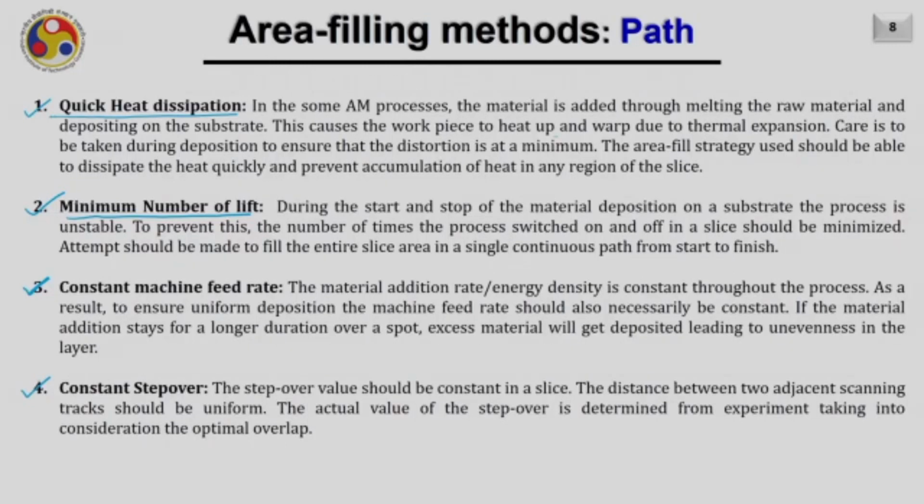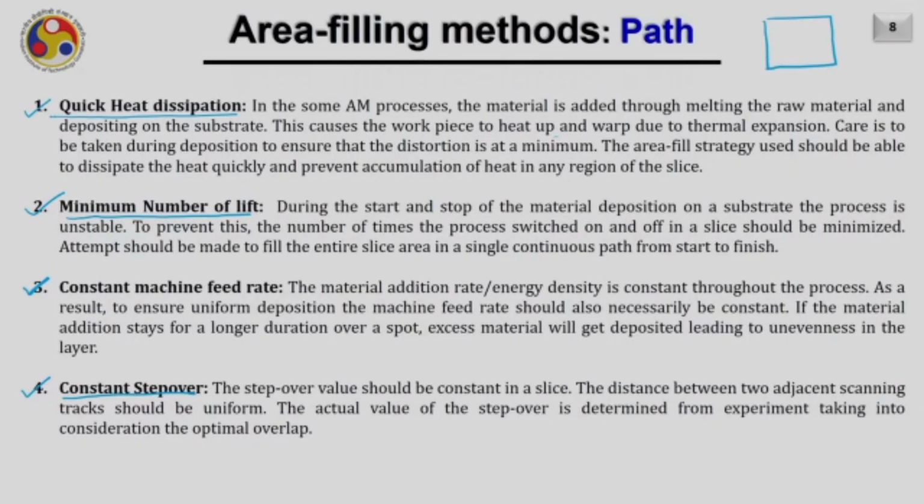Fourth and the most important one is constant step over. The step over value should be constant in a slice. What is step over? Step over is nothing but the distance between two consecutive passes in the XY plane. So for example, if we are filling the area inside this rectangular slice and this is the first pass, the next pass will be at a distance.